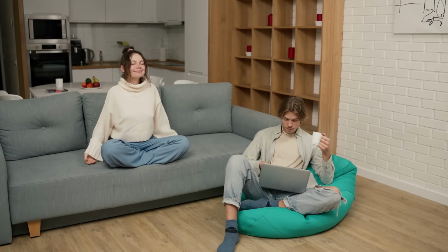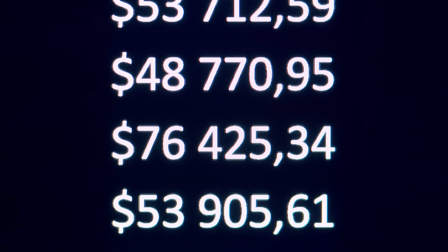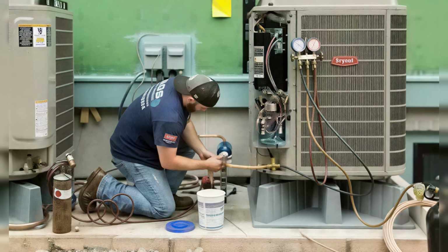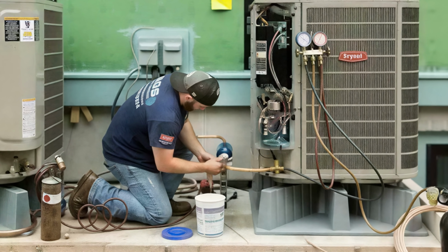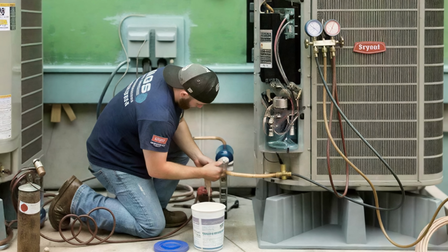The reason your thermostat is lying to you is simple. Comfort is subjective, but a service call is expensive. When an HVAC technician installs a unit, they want one thing: to never hear from you again. To ensure that, they leave the deadband or differential at the factory minimum, usually 1 degree.